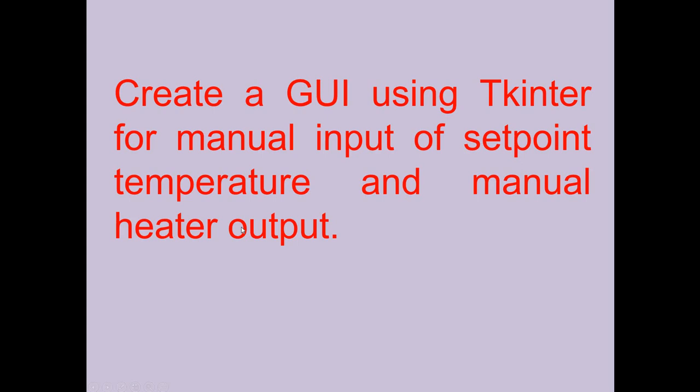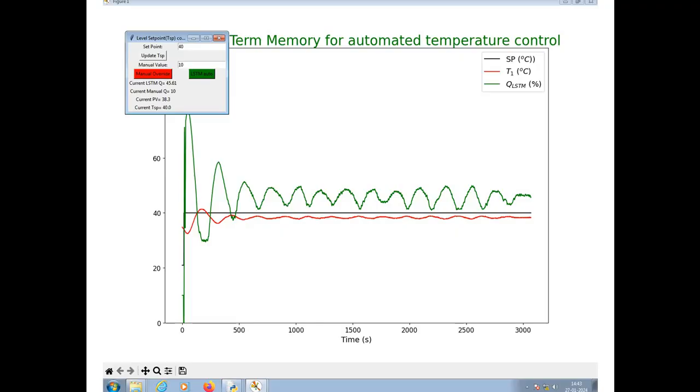Now how do you create a UI to read the temperature and see how the profile is going to look? You have two methods of doing it: one is auto mode, the other is manual mode in PID. In manual mode you just give a fixed power to see whether the system is working, like 50% of the power. It's like giving a unit step function, so you can test the system. Otherwise, auto mode means PID will completely take care.